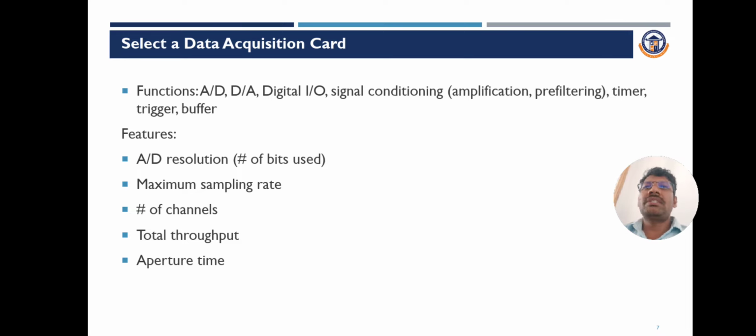So here the measurand is converted into an analogous electrical signal, which is performed by the transducer. A transducer in general is defined as a device which converts one form of energy to another form. In electrical measurement, this definition is limited in scope: it is a device which converts a physical quantity into an electrical quantity. A physical quantity to be measured is first sensed or detected by an element which gives the output in a different analogous form. This output is then converted into an electrical signal by a transducer.